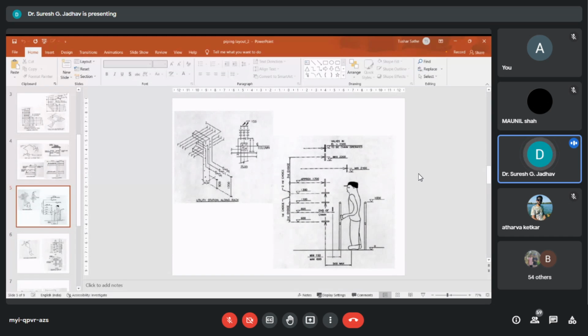So here we can see the chain operators can be marked from the 600 elevation, 800 elevation, 1100, 1300, and approximately here we have to consider the 1700 elevation. So valves located at low or high locations can have extended stems to reach the access levels. One thing must be ensured: the stem will not be oriented below horizontal lines. This is very important. If you extend, then utility lines and pumps will be affected.